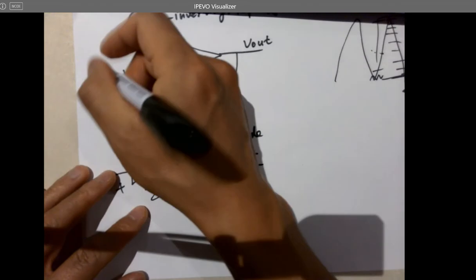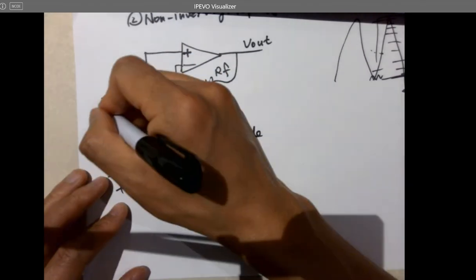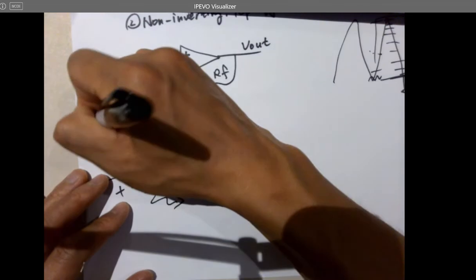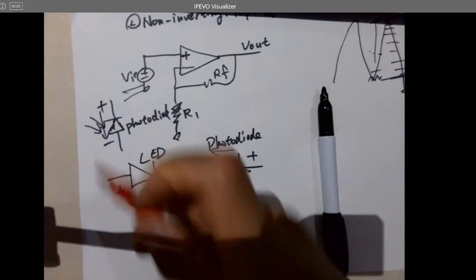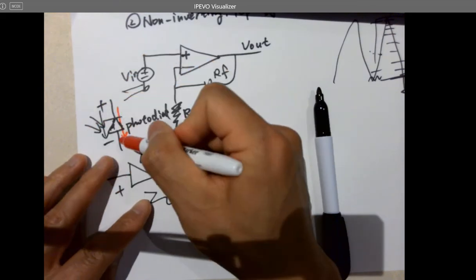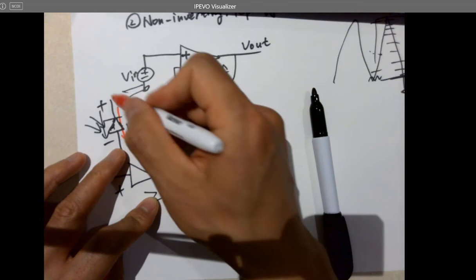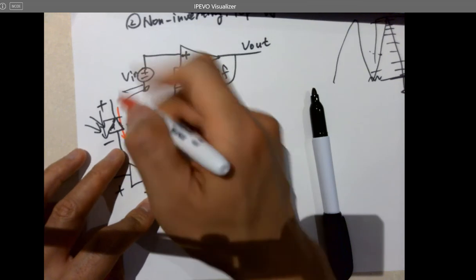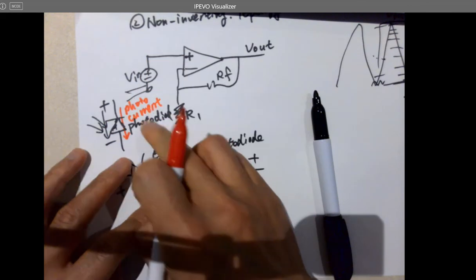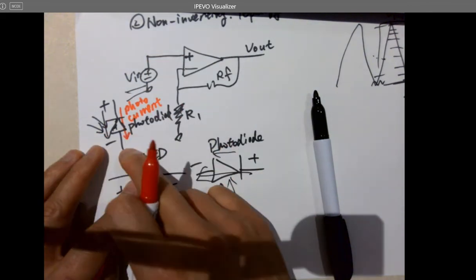However, a photodiode, you just reverse bias it. Even though there's no current flowing through statically, whenever it receives light, a little bit of current flows in that way because we have that reverse bias. It's pumping the current from top to bottom, and that photocurrent is proportional to the light intensity. That's how you can sense light.